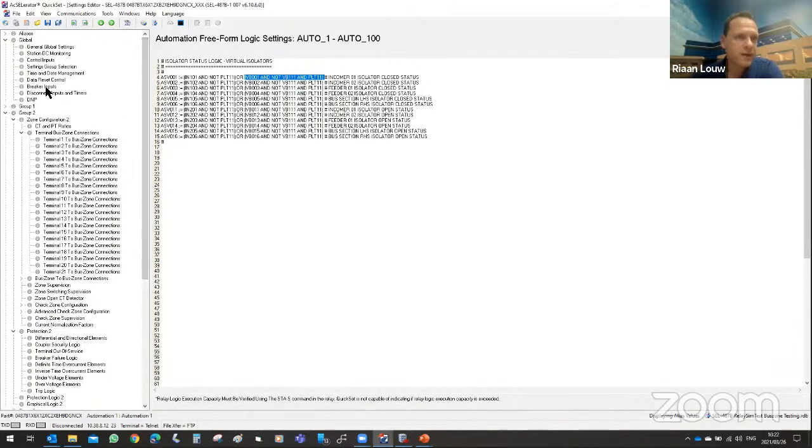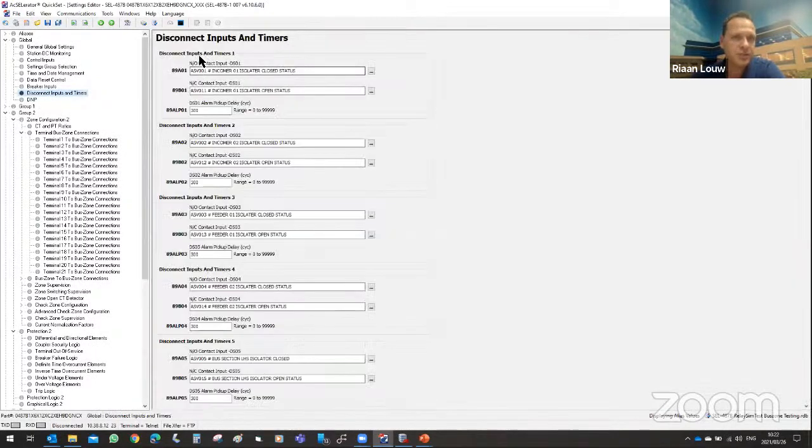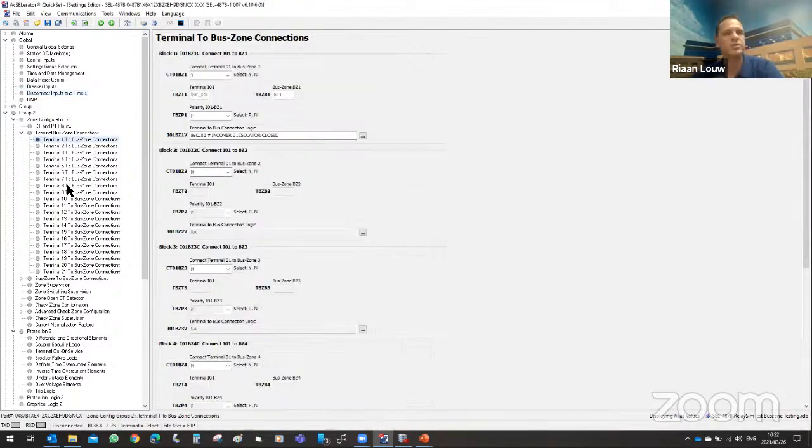So once you have configured all these disconnector inputs to the respective positions on your relay, you can use these disconnectors in your terminal switching logic. So then I'm using that 89 CL01 to switch in my CTs into the respective bays. Now, I'm not going to spend a whole lot of time explaining and detailing the logic here. I just wanted to make you guys aware that we are using two sets of logics here.